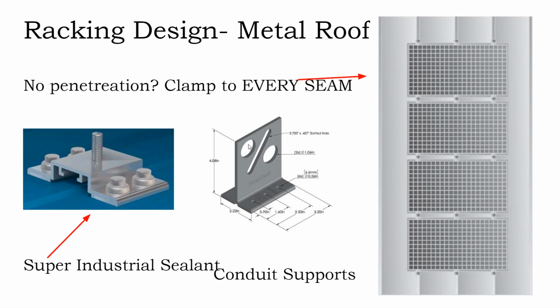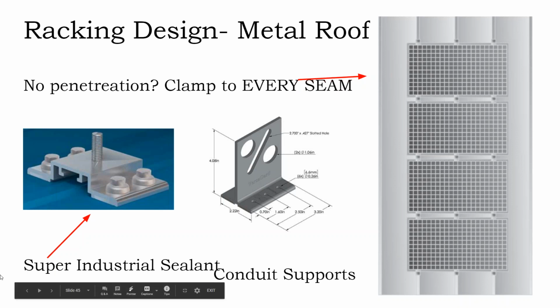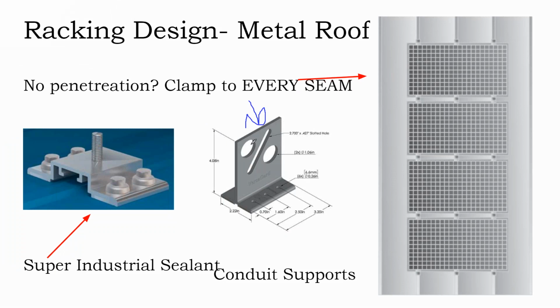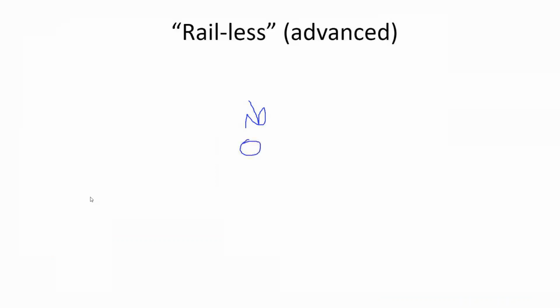There are products for metal rooftops: clips, seams, penetrations, attachment points, and in fact, not just for standing seam, but there's products for screwing into the metal on a traditional metal rooftop. And I actually like these products better because a clip just clips to the top of that metal surface, whereas a positive penetration goes all the way through into the rafter or the purlin. This is a product for elevating conduit up off of the roof surface of a standing seam metal rooftop. So the industry's come a long way in terms of product selection.